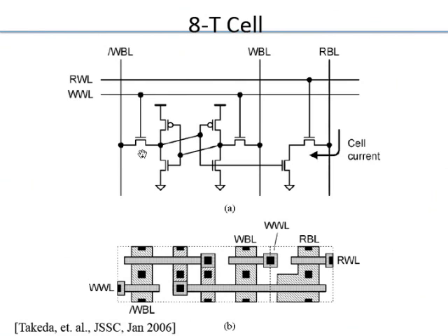The reason is basically, if I want to write into a cell, I have to push a 0 into the cell. So if I want to write a 0 here, I need to push a 0 through here. But if I want to push a 0 here, I'll have to push a 0 from here. Remember, because I can't push a 1 here. Pushing a 1 through NMOS doesn't work well, because NMOSs have this threshold drop, right? So you really write a cell by pushing a 0.